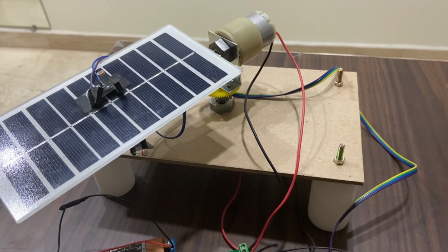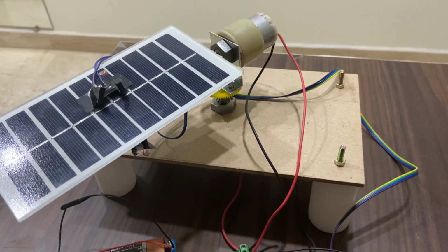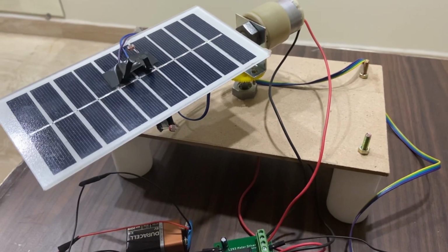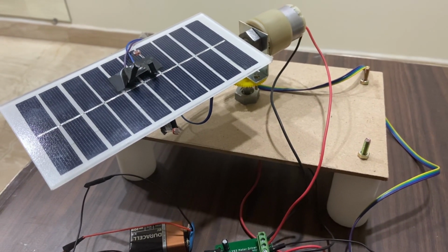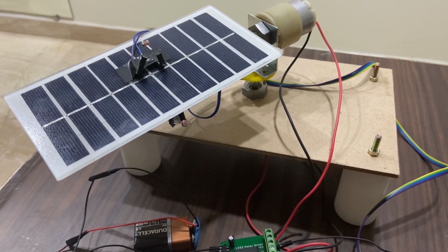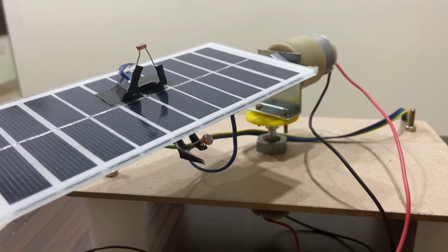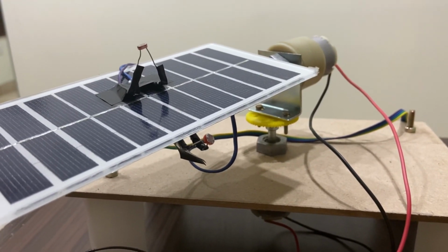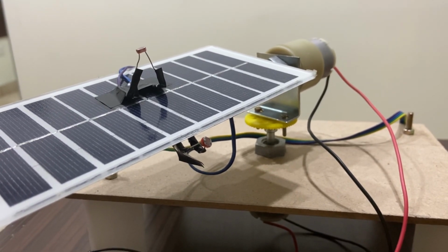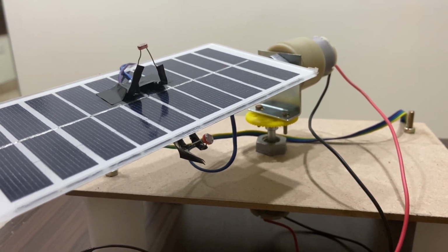While programming the Arduino, we have to keep certain cases in mind. For case 1, let's say the light is incident on sensor number 1. In this case, the top motor must rotate the solar panel clockwise about x-axis until sensor number 1 senses maximum light intensity. For the second case, let's say no light is incident on either of the sensors on the solar panel. In this case, the base motor should rotate the solar panel in anti-clockwise direction about y-axis till light falls